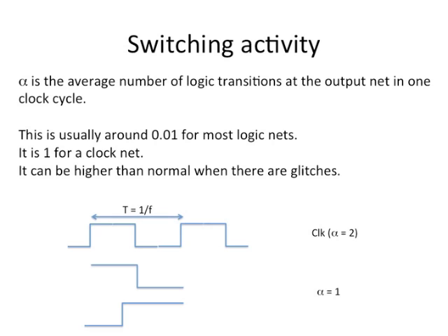No, it's not desirable, but you could have it because you could have a logic net which is somehow chattering up and down due to certain problems in the way the circuit is designed. Jitter is not the right word, but essentially you could have bounce. And in those situations, alpha could be more than what it is supposed to be because there are extra spurious transitions happening.